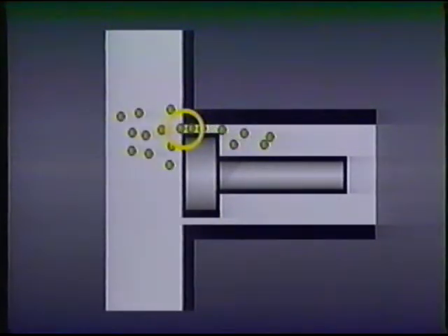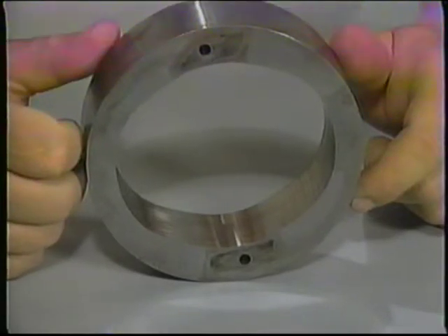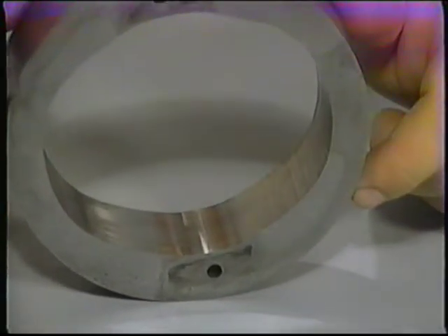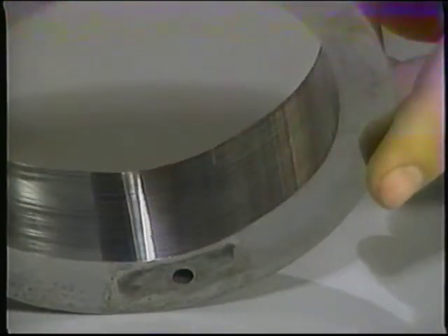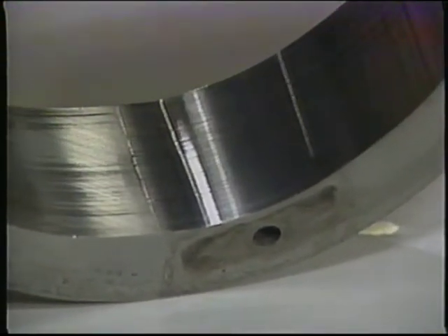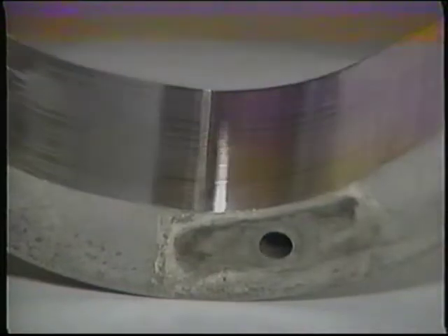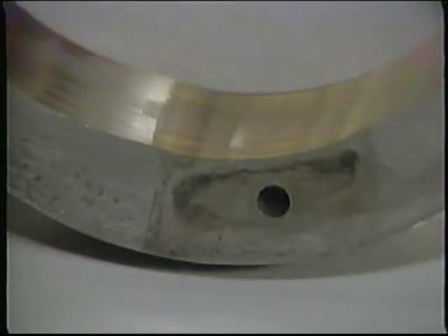Very fine particles can build up inside clearances like silt in a stream, clogging valves. This is especially true if the valves are not cycled regularly. Medium-sized particles can work into clearances, break down lubrication, and cause excessive wear. Large particles may actually block openings, plugging up the system. Any dirt that mixes with hydraulic fluid makes a very effective grinding compound that will cause rapid wear. This is especially true in spots like this, where the vanes of a pump ride on the cam ring.